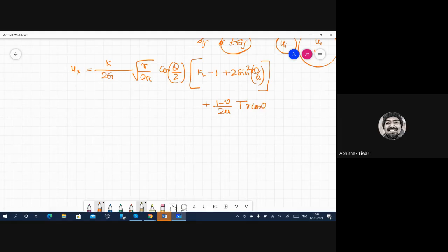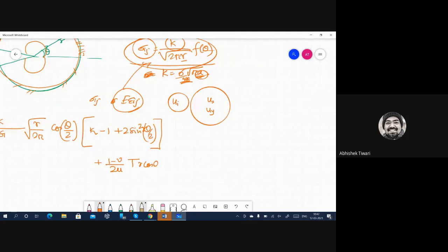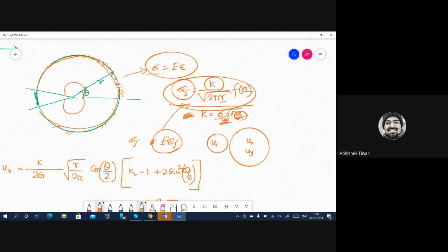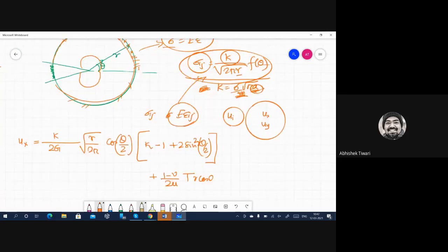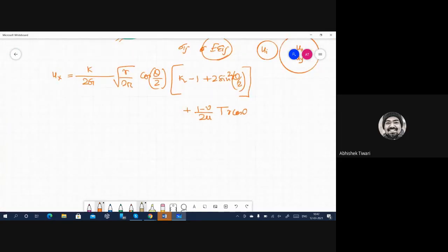So this is another benefit, that you can actually define systematic values of T stress also, but we will not deal with T stress too much. Actually none, so I will remove this part. But you can do it systematically. If you want to have 10 megapascals of T stress applied, you can do it by using this equation, applying exactly the same amount of displacement, and you ensure the condition that this much T stress is applied.